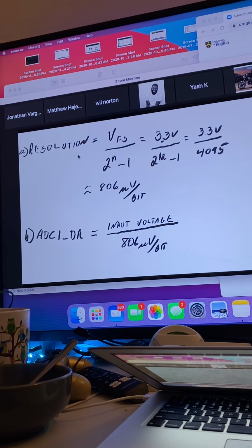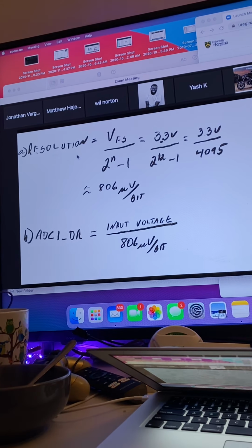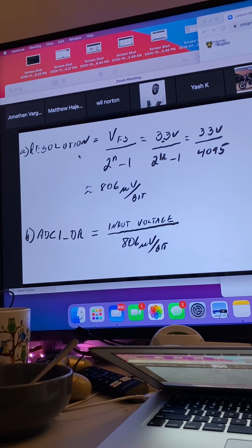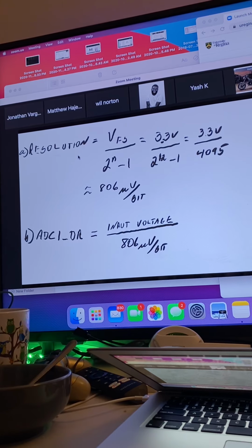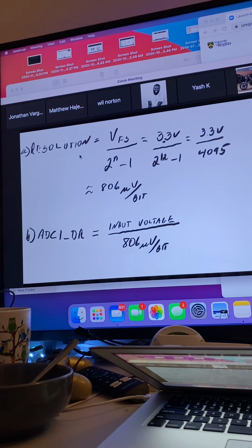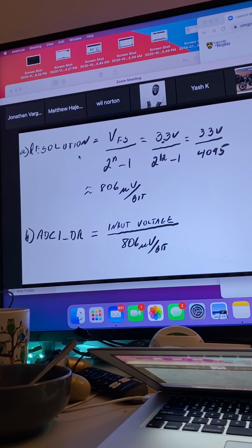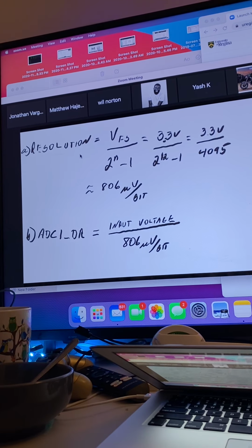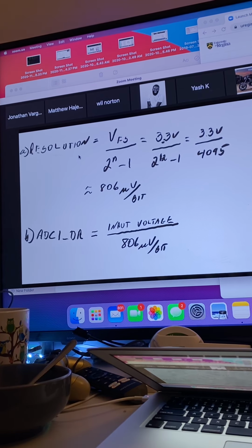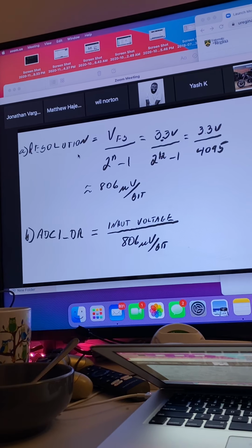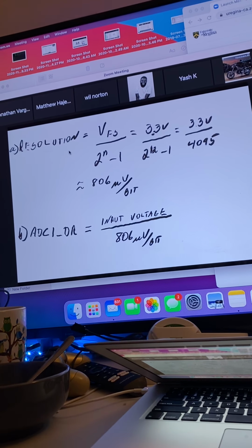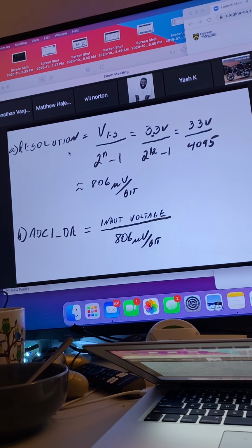You'll need to show pin numbers on the micro, so how are you going to provide certain things? And at this point, the only question that we've never really gone over is which pins will be providing our PWM. For those of you with a Nucleo board, the likelihood that your PWM will occur on timer 3, channels 1 and 2, is fairly high.